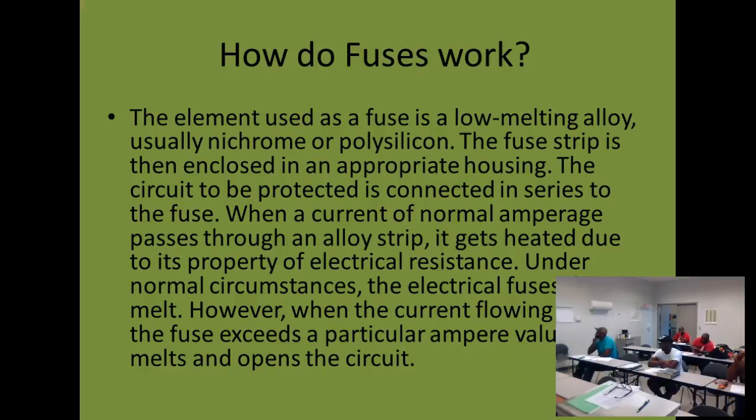Had a circuit breaker there. Comes down here. And let's say we got a fan motor. So we got a compressor. We got a transformer. Okay. You shut this circuit breaker and it trips. Right? And it's going to trip because it's telling me somewhere in here I got no resistance. This power is connecting to this power somehow. Although we have a load in every circuit. It shouldn't, right?